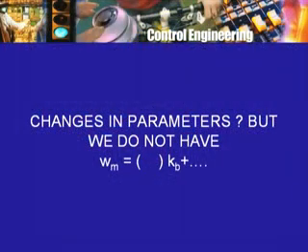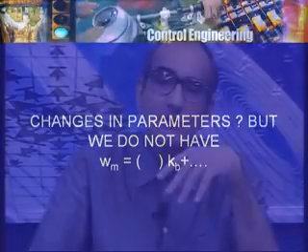As you will notice from the expression, delta has Kb in it, and the numerator in the multiplier for Ea also has Kb in it. So it is quite possible that Kb occurs in a not a linear fashion, and therefore omega m cannot be written as some expression which multiplies only Kb plus something else, so that we can look at change in Kb, say 10% change in Kb, or Kb changes by this much, what will be the change in the speed.